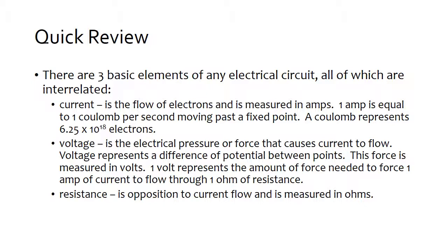Another element in an electrical circuit is voltage. And remember, voltage is not the movement of electricity. It's the electrical pressure or the force that causes current to flow. You can think of voltage as a difference of potential between 2 points. You'll have one terminal that's got an excess of electrons, so it's got a negative charge.